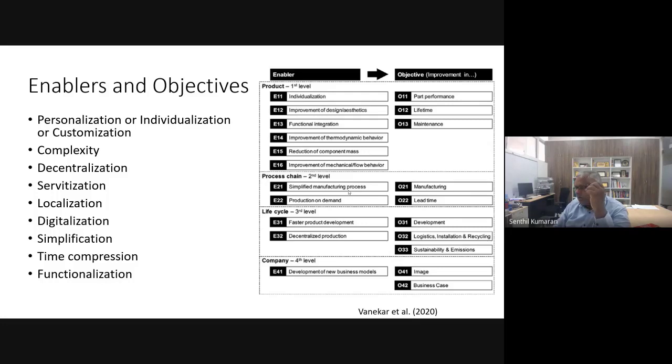So that part, if I want to make it for individual patients, I have to take it. So let's say you are doing it in injection molding. In injection molding, you need to make a mold. The mold is going to be extremely expensive, and you have to throw away the mold once the patient goes. And if it's a 1 crore mold, you have to charge him 1 crore for that particular operation, which is prohibitively expensive. So no one will buy. There is no market opportunity for such a thing at all. So that's where 3D printing comes in.